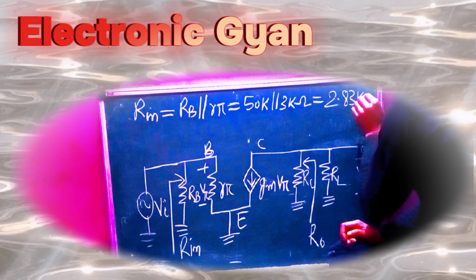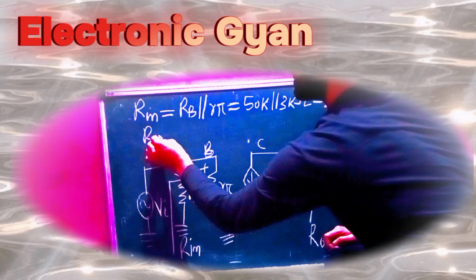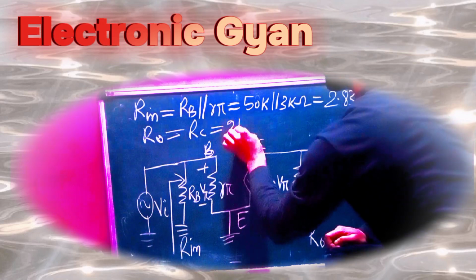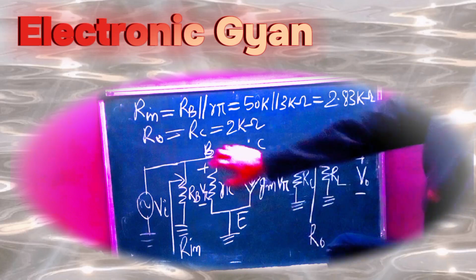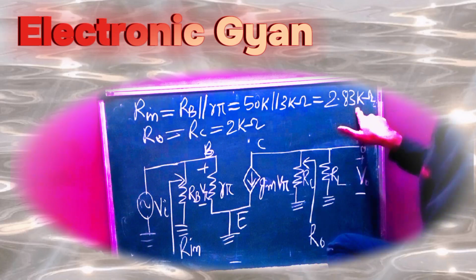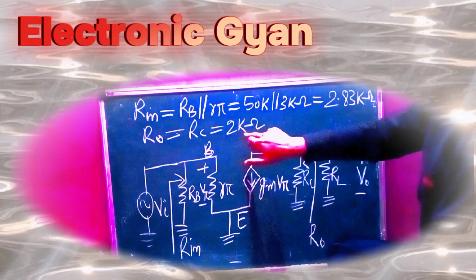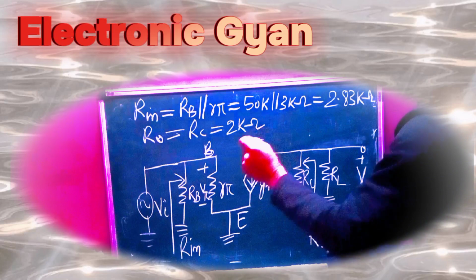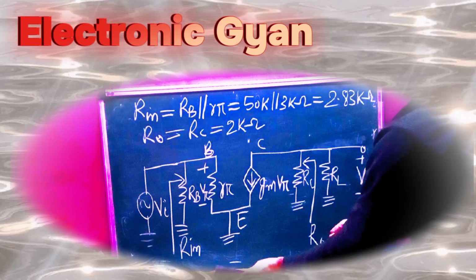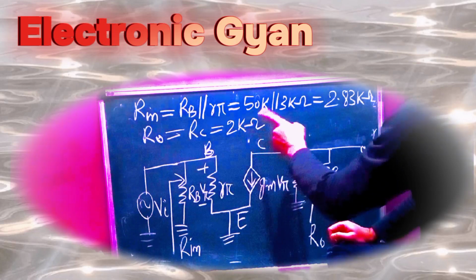This is my input resistance, and my output resistance is similar to RC, which is my 2 kilo ohm. So the input resistance for this common emitter amplifier is 2.83 kilo ohm, which is the parallel combination of RB and R pi, and R0 is my RC, just RC, 2 kilo ohm. Now here we are going to calculate the voltage gain of an amplifier. Input resistance we have obtained, and output resistance also we have obtained.